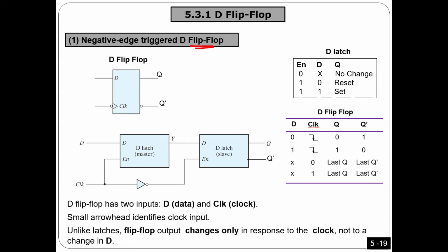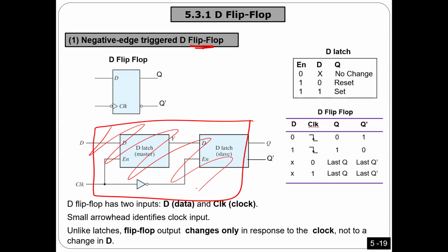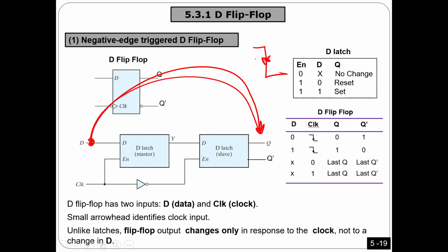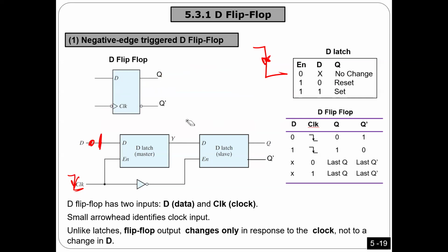So what happens here is, look here, guys. This is the flip-flop this way. Again, this one is negative edge. So what happens here? Whatever you have here, I have to see it here. Whatever you have here, I want to see it here, every time there is a falling edge. That means if I put one, this one has to jump from here to here when there is a falling edge here. Okay, I will tell you how it happens.